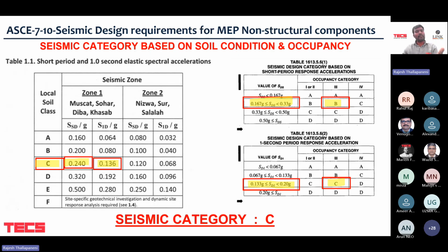The same principle happens in a large building. Assume that you have a 30 to 40 floor building and a seismic incident happens. It will not oscillate so fast. It will oscillate like a pendulum. It goes and then comes back. So the behavior of seismic incident is very different. A short building oscillates vigorously, whereas a larger building acts as a pendulum. Both scenarios have to be taken care of when we talk about the seismic incident.